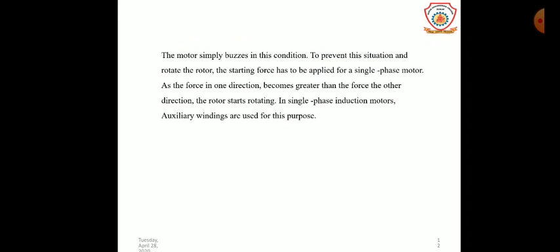The motor simply buzzes in this condition. To prevent this situation, a starting force has to be applied to rotate the rotor of a single phase motor, so that the force in one direction becomes greater than the force in the other direction. Then the rotor starts rotating. In single phase induction motors, auxiliary windings are used for this purpose.